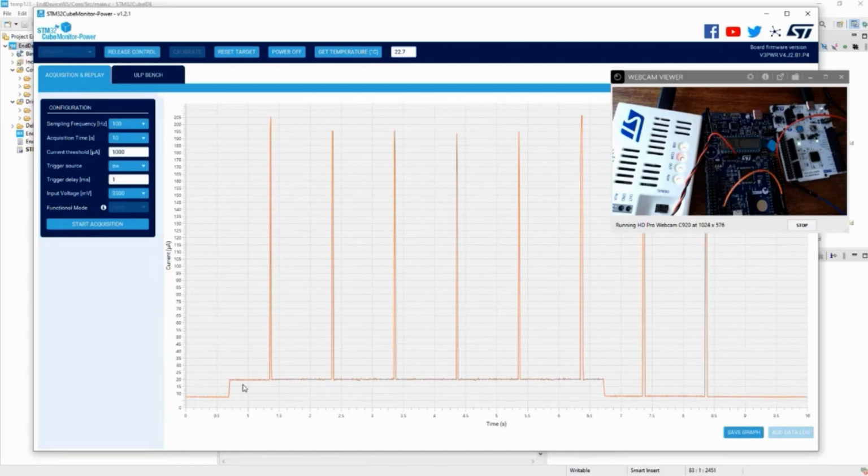So you see, in fact, when you start to have some edge, PWM edge, you have the LP timer interrupt that is coming very regularly, so the consumption increases. You also activate the RTC interrupt, so you have this RTC interrupt that appears here. You change the duty cycle, it's still a bit the same consumption because it's the same processing. You update under the RTC interrupt the duty cycle message. And when you go back to idle, you stop receiving the LP timer interrupt here.